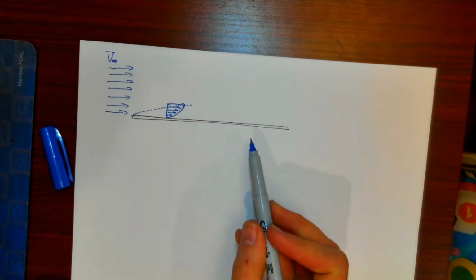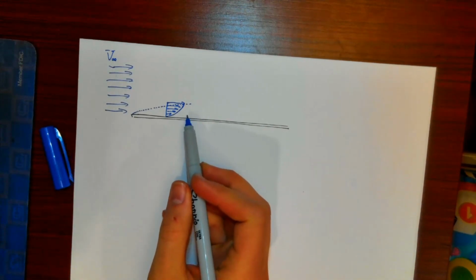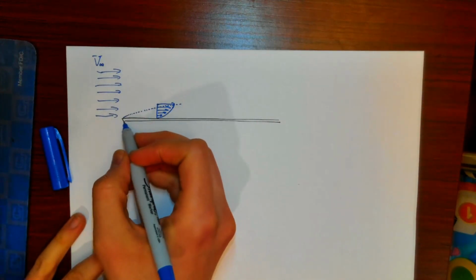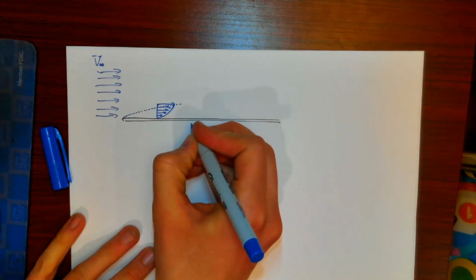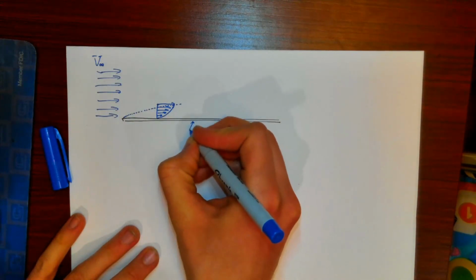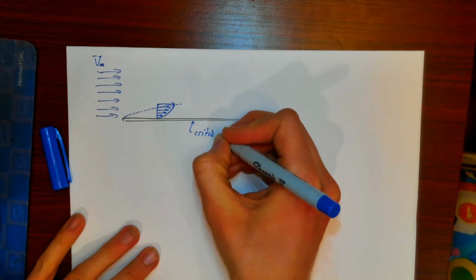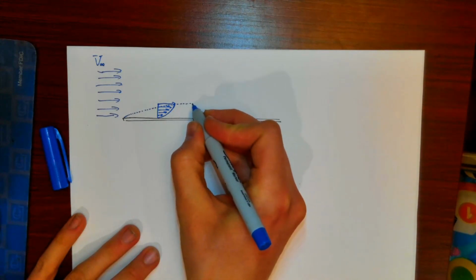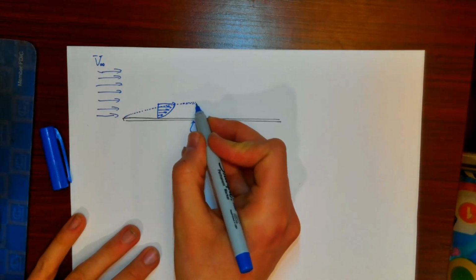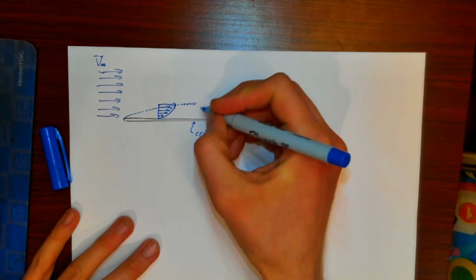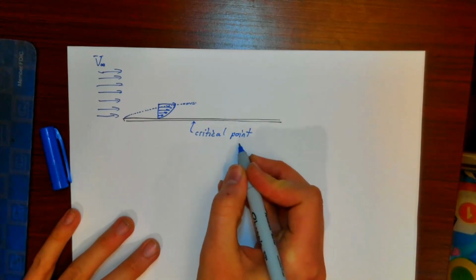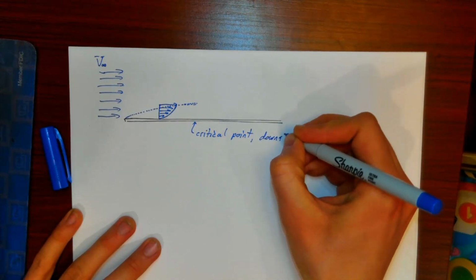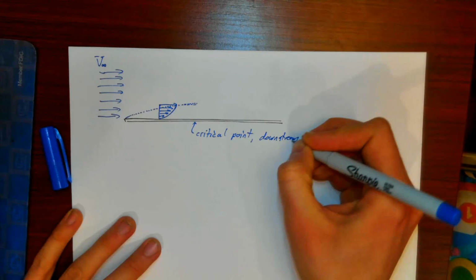It turns out that for flow past a flat plate, you can have laminar boundary layers and you can have turbulent boundary layers, and there's a transition where the flow at the upstream part of the plate often starts out laminar, but after a certain critical point at the plate, this laminar boundary layer grows and grows and gets too big, and eventually that flow always gets tripped to turbulence. So there's a critical point, and then downstream will be turbulent.